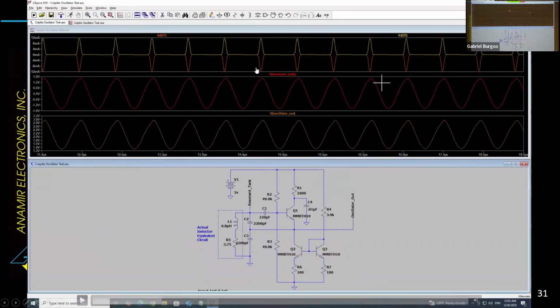I can see what the currents are doing as a function of time. I can see what the voltages are doing. You can see here the transistor is kicking the resonant tank circuit, the resonance of the inductance and the capacitance. It's giving us the oscillation, and the transistor is kicking that just like a pendulum clock has a little kicker that kicks the pendulum. Some idea here, and we get a signal.